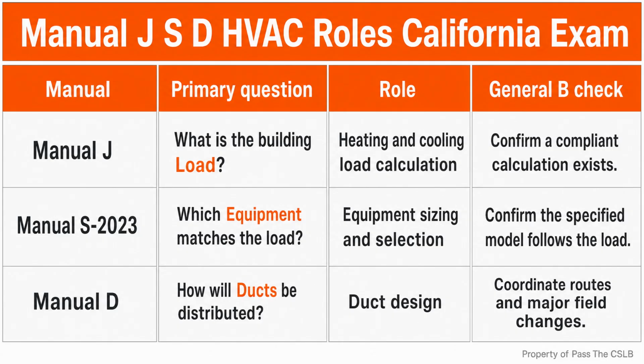Outdoor design temperatures also cannot be picked casually. The source material directs them to Reference Joint Appendix JA2 or the American Society of Heating, Refrigerating, and Air Conditioning Engineers Handbook. The project location matters because California climate conditions vary. The approved source supplies the outdoor design value rather than a salesperson, owner, or contractor choosing a dramatic number to justify larger equipment. For additions, the source material states that block loads are permitted for calculating system sizes.